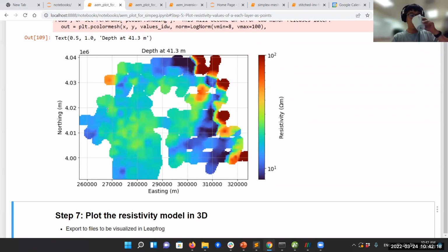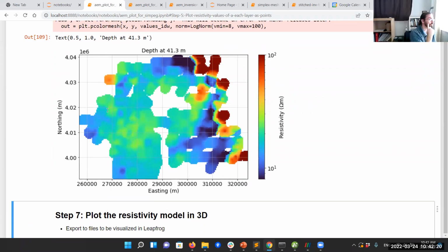Correct. But my question is, some of your soundings are very far apart. When you stitch things together, was there also a maximum distance for regularizing only between two soundings if the distance is less than that, like, I don't know, 100 meters between each sounding or something? Because I can imagine, here at the center for example, if you try to regularize on the side, it's going to be a fairly big jump.